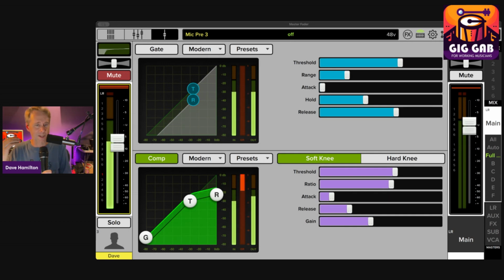In live sound, especially if you've got live drums and amps and stuff on stage, you need to have a minimum level of sound. And so the idea behind compression is that you bring down the peaks so that you can bring up the overall level. The reason we call it compression is that you are taking the dynamic range of the signal and compressing it down to be less of a dynamic range, meaning less volume difference between the quiet portions and the loud portions.